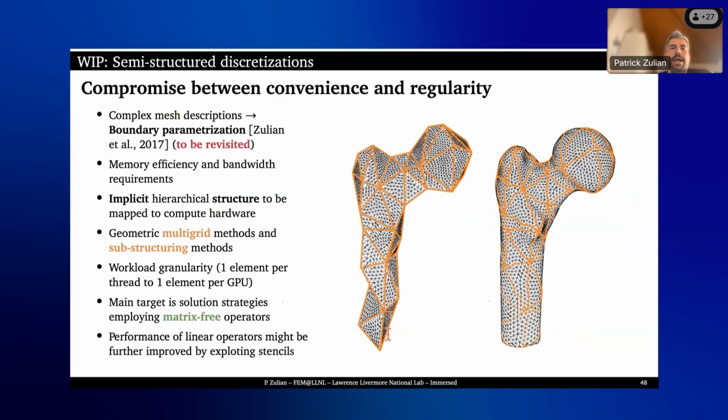And okay, someone once told me that they don't want to use multigrid because they don't want to solve problems inside a cube. But my answer is that for any type of mesh, there is a reparametrization you can do to describe that mesh quite accurately. This is something we did back in 2017, a surface reparametrization, where we construct a mapping from something like this to something like that, starting from the original mesh.